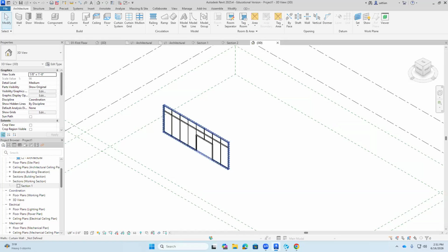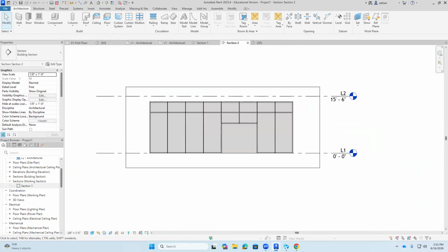Then you add the curtain grid elements. Notice I created a section, and then within the section view, I created each one of these lines. I used the array because it's not letting me choose the distance, it's only letting me choose how many. So just click on one and then type in 4 foot 10 1/2. Now how many copies do you want? 7. There you go.